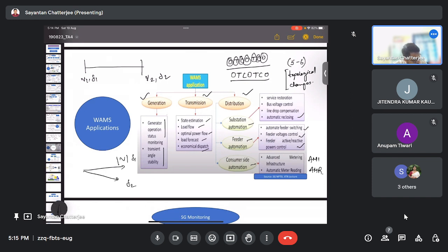So this angle change would give us information based on the bus voltages. It can also be done using the PMUs, means optimal PMU placement, because if we have a PMU here and the line parameters known, then we can directly find out the bus voltage magnitudes and phase angles on this side based on the line voltage drops.